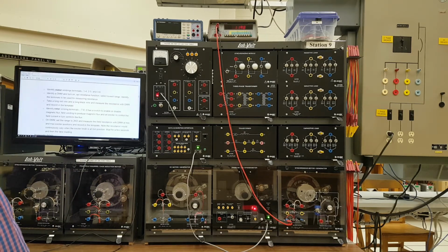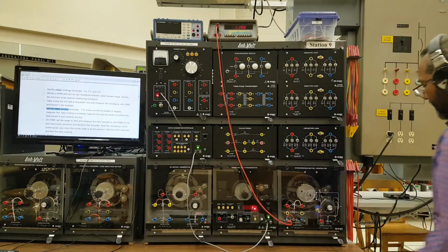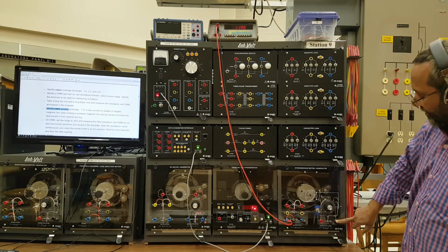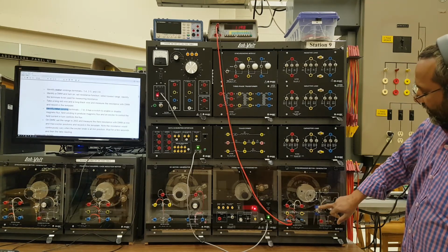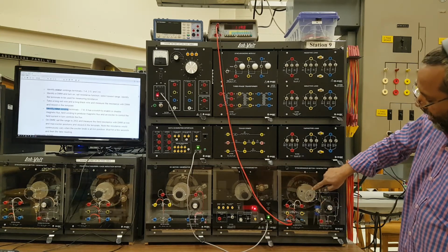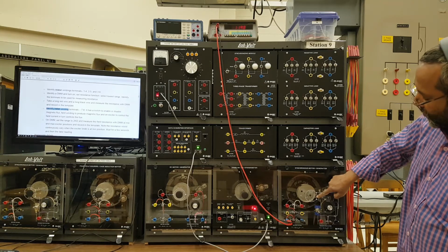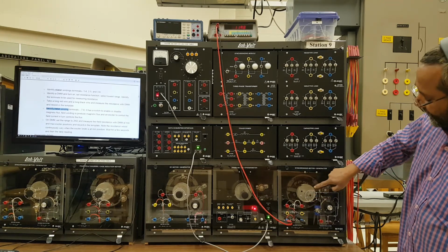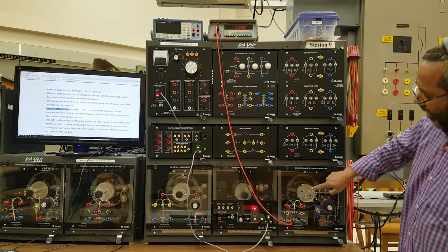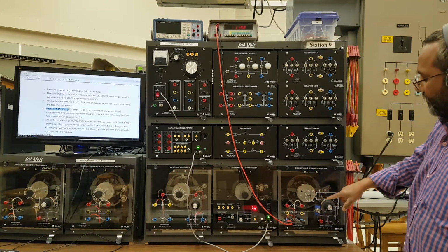And then the next instruction says identify the rotor terminals. These are the rotor terminals here, 7 and 8. There is a switch here, and there are 4 poles. The top one is the north pole, and then there is south pole, north pole, south pole. It is the same winding going through all the poles, but in series.